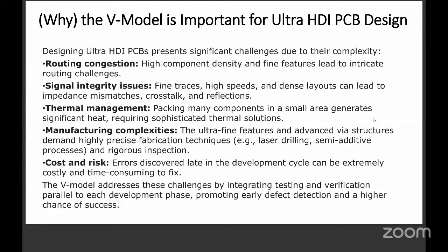Routing congestion, signal integrity issues. We are almost hitting microwave type of signal integrity problems at gigahertz range. Thermal management is always there. Things get heated up while manufacturing the PCB, as well as assembling, as well as in service.